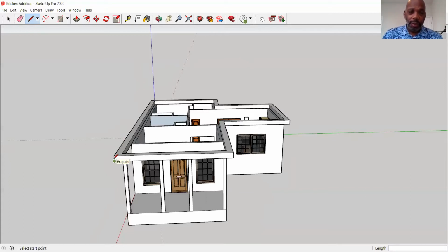The span is always calculated as being half of the total distance, which is 18 feet from here to here. Half of that is 9. I multiply that 9 by the roof pitch, 10 and 12, which gives me 90 inches.